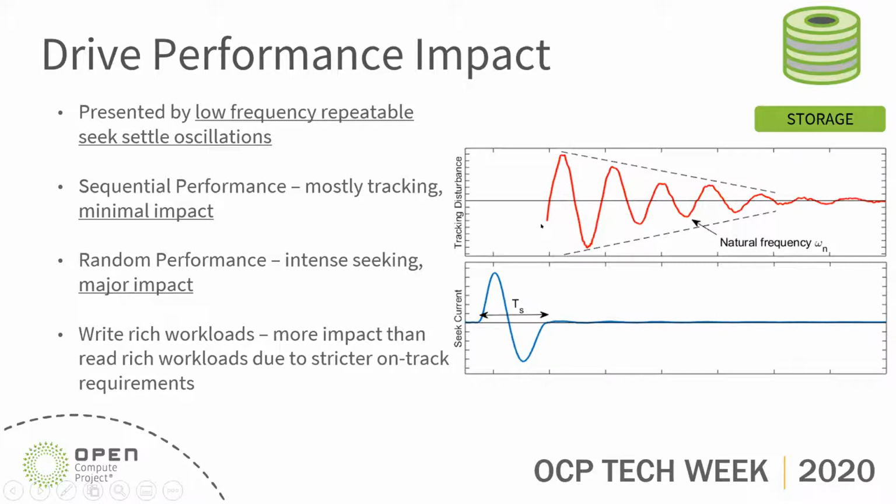Historically, vibrations and acoustics were the dominating factors, and the mount dynamics was buried under that disturbance. But as TPI is increased and we are dealing with much smaller tracking requirements, the mount dynamics becomes quite visible. And in future systems, when fans will become even better, or we talk about using immersion systems, which have virtually no acoustics and mechanical vibrations, this will become the main dominant source of drive disturbance.